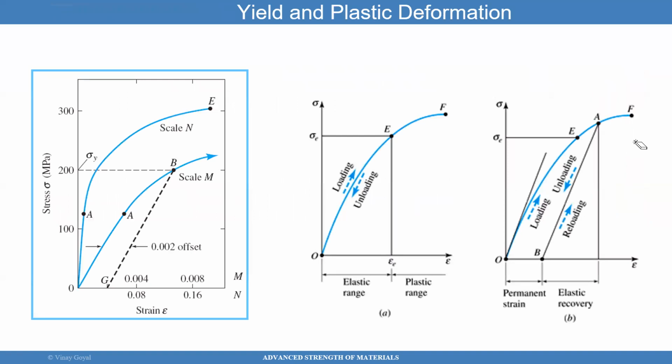Another thing I want to point out is how the stress strain curve can be looked at. If I magnify in here on the stress strain curve, you can see that when I go up to a particular load, I would like to define yield in a smart way so I can use it for design. And why is that important? If I choose yield here or yield here or yield here, it's unclear where the nonlinearity starts. And so rather than being arbitrary about that, what people have thought about doing that works very well is to take a 0.2% offset. So you take this line here, and you move it 0.2%, and you draw a line until it hits this curve, and then we call that the yield strength of the material.